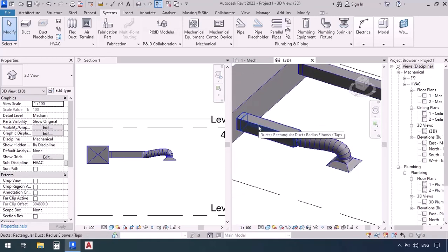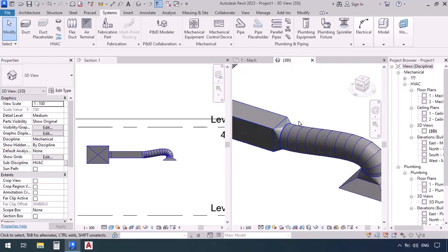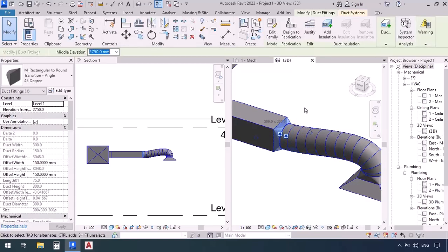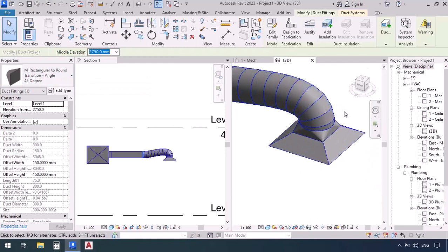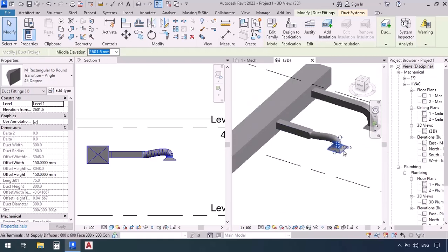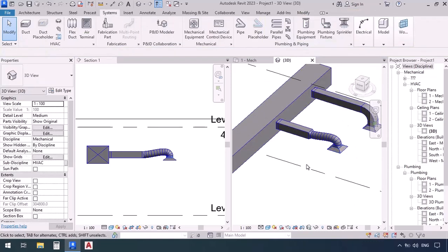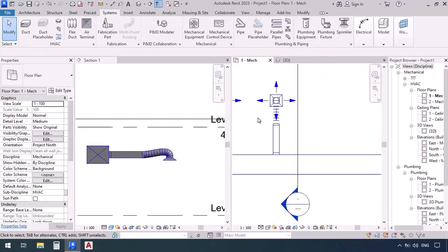As you can see, we have the tab, the direct duct, and you know our starting duct was rectangular. So when it was trying to connect to a round one, here in the middle it gave us a rectangular to round transition. If you recall, we've talked about that before. Now, to finish the process, this round duct was trying to connect to this square terminal, so it used a transition to connect these two. It was a round to rectangular, or round to square transition. So, as you can see, it applies the needed transition automatically.